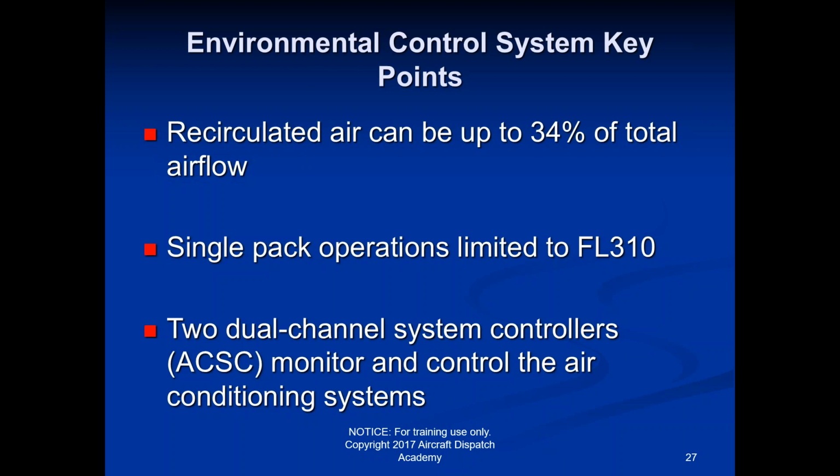Single pack operations, this is one you need to know and remember. Single pack operations are limited to flight level 310. So if one of the packs is out, my max altitude is going to be 310. And ultimately that will create other problems associated with having to fly lower. You fly lower, you burn more fuel. I mean, it's going to affect everything.